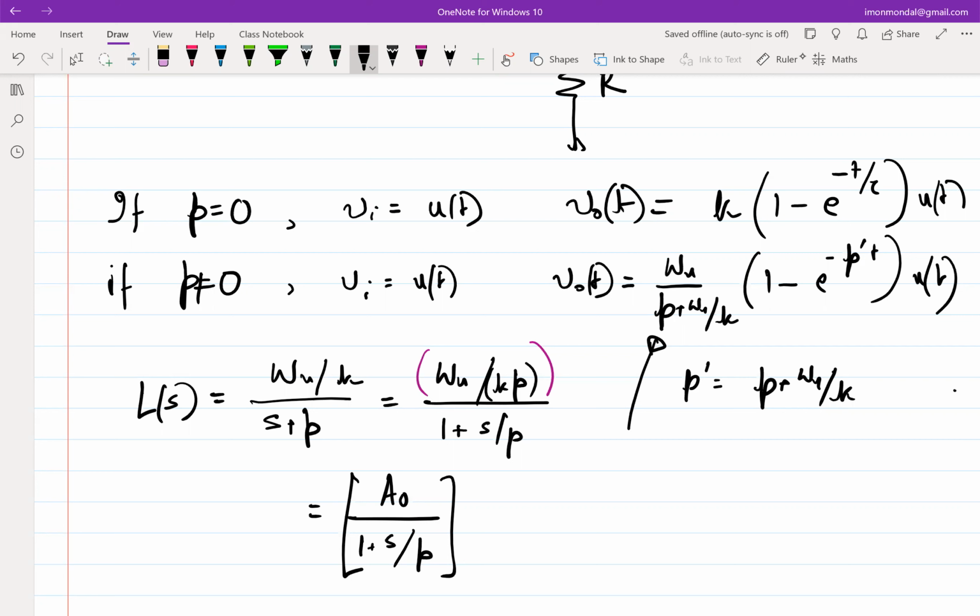Like in that case, the error should not be 0 because we are applying the AC signal. Yeah, when I say ideal, it's an ideal integrator. And even an ideal integrator will not give you 0 error signal, right? Ideal integrator gives you 0 error only at DC, right? So that's actually a good point. When we say ideal integrator, we covered it in the previous class also. An ideal integrator gives you ideal output, that is K times amplified output, only at DC, because an ideal integrator behaves like an infinite gain block only at DC.